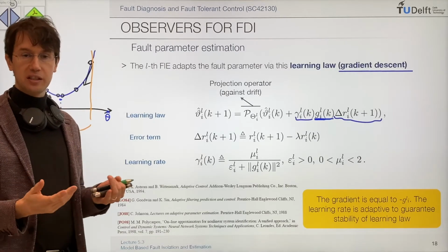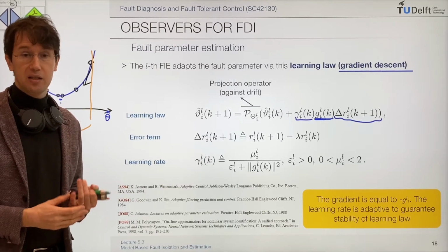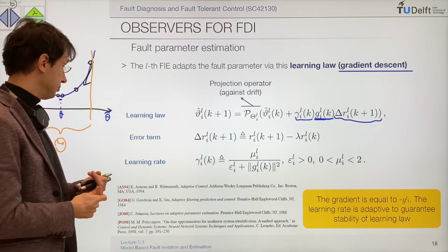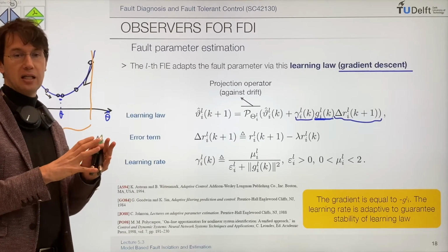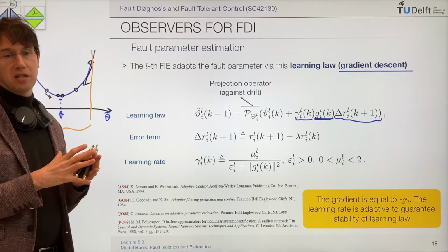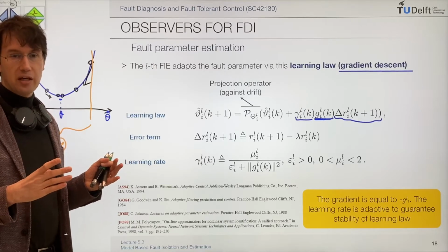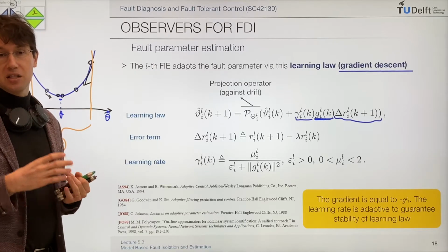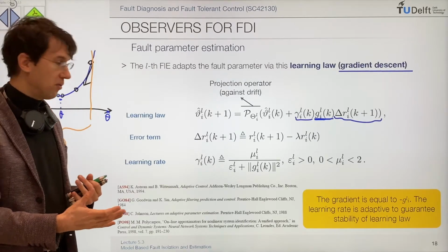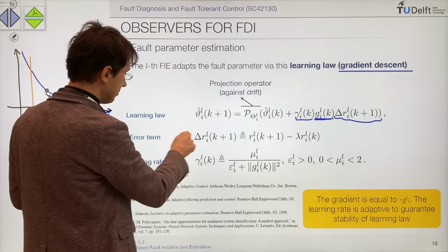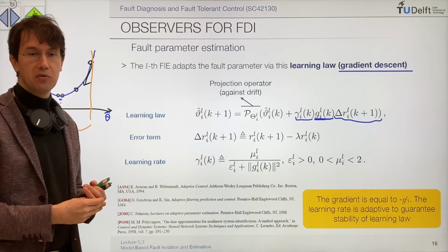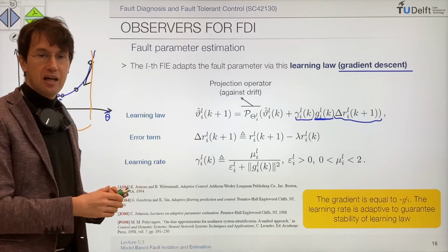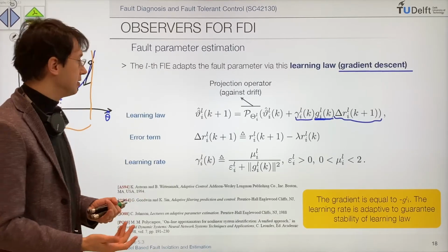So whatever value of theta, when the fault is not matched, it is not making the residual small. And this is causing a phenomenon called parameter drift. So you're trying to learn a parameter that actually has no effect on your error term, and so you continuously update it moving in some direction, and this can get unbounded, basically.